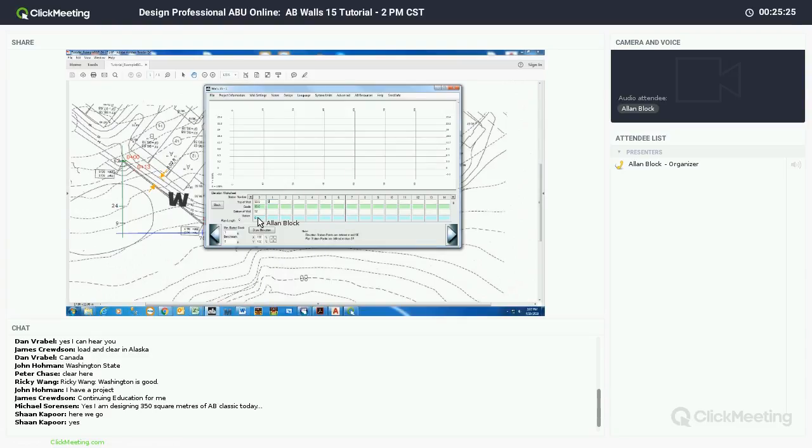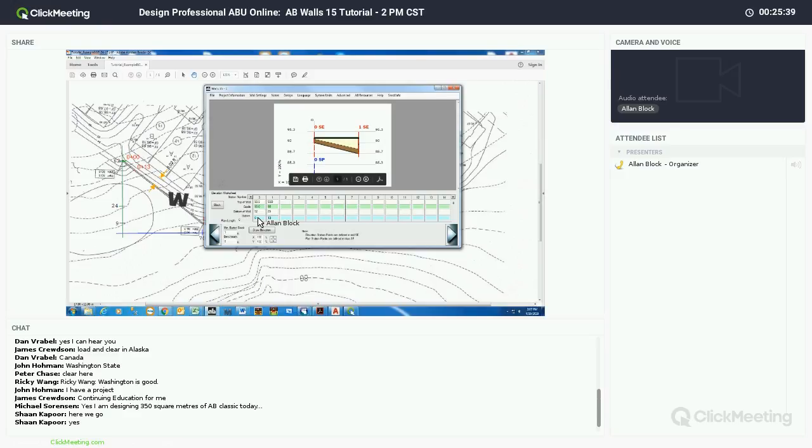And I'm going to look at station 13, where my top of wall hasn't changed, but my grade value has, based on the contours. Now when I hit tab, fill in the station, and hit Enter at station 13, it's going to draw my wall based on those 2 points in the visual screen above. What we're looking at is just the representation of how the wall will look. As we fill in more points, that's going to fill in more.